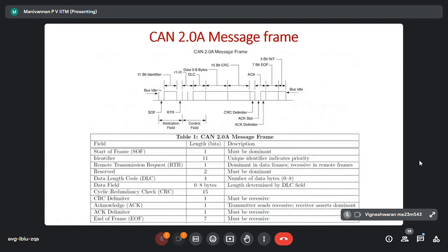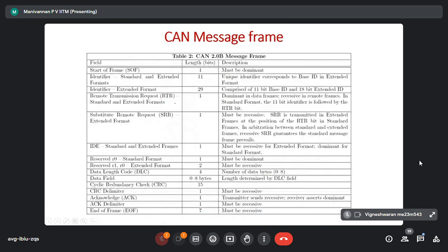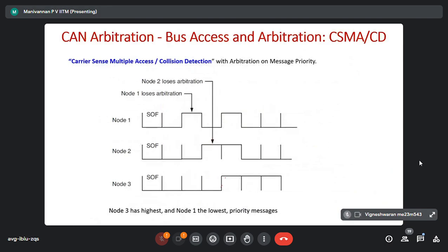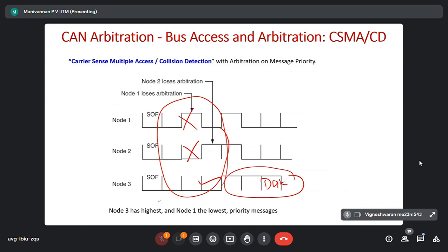See, first all people will start by sending the startup bit, correct? Then arbitration, the ID, correct? They were competing, correct? They are fighting for who will control the bus in the arbitration field. Correct? 3-bit arbitration. Instead of 11-bit, I am showing only 3 bits for understanding purposes. Once this one becomes master, he is transferring digital data because they send bit by bit. This is serial communication. Please note that CAN, LIN, FlexRay, MOST, all are serial communication.